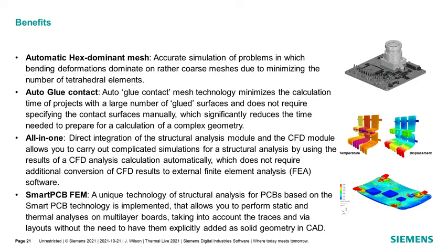There are some benefits to this technology and implementation that I'd like to briefly discuss. One is that the meshing approach in SimCenter FloEFD for the structural analysis is automatic, and it's a hex dominant mesh. So generally speaking, I think hex mesh gives you the most accuracy for the least amount of mesh. So generally it is a preferred meshing format compared to other topologies.